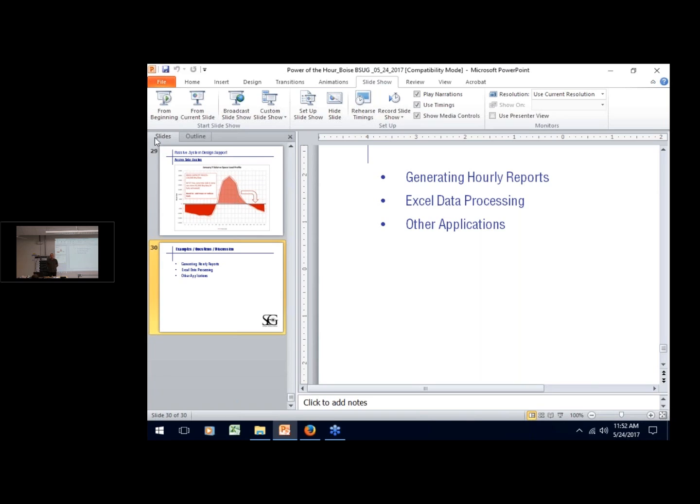It will reference a weather file, which may or may not have design day conditions embedded in it. The file has the data in it that it has in it. So you're going to have to reference a weather file, and you're going to have to specify a simulation period of at least 1 hour. And that's probably not your design day. We would typically just rely on the default simulation period, which is the entire year.